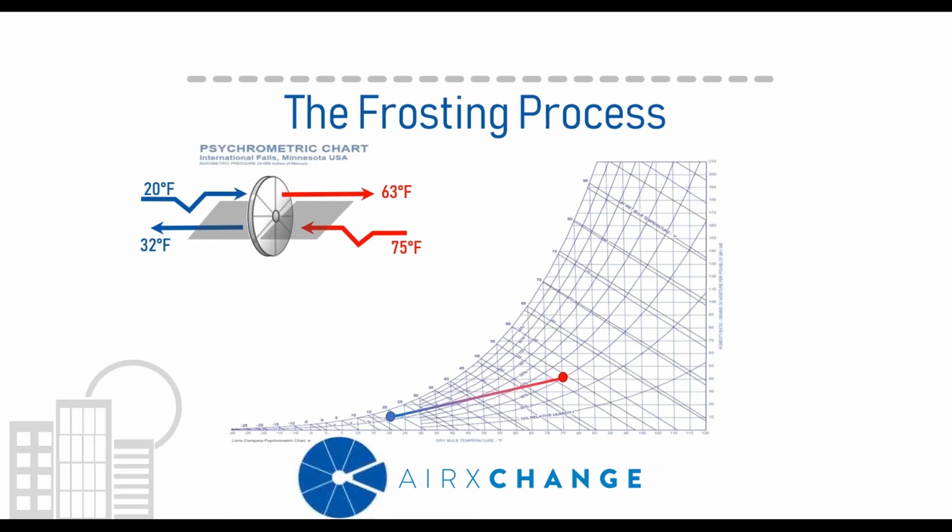At any given point in determining how effective the wheel is, the leaving supply and exhaust is going to end up somewhere on this line. I'd also like you to take note of the different state points, and in this particular case, which airstream holds the most amount of humidity. Well, if you remember from a couple of previous slides, I said it starts where very dry air moves up to more humid air. You can see that this point, which is your exhaust point, has the most amount of humidity, and it's good to keep that in mind as we discuss the frosting process.